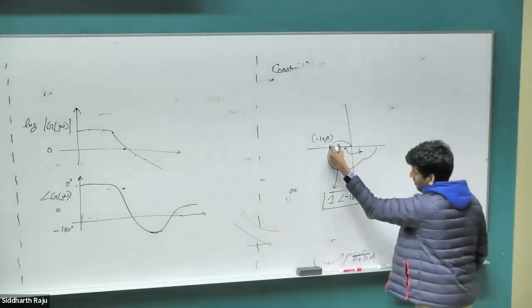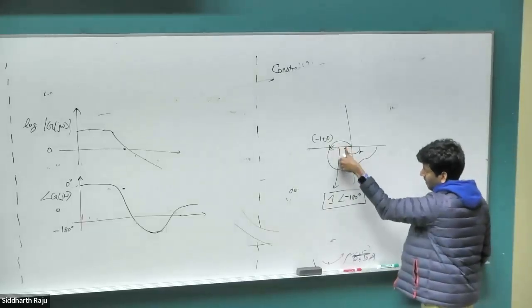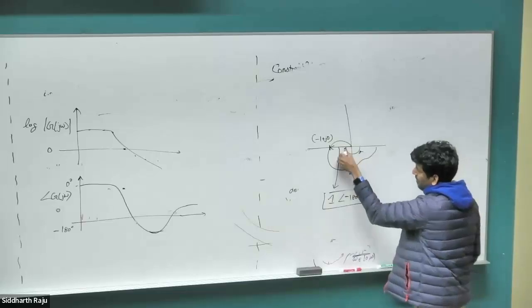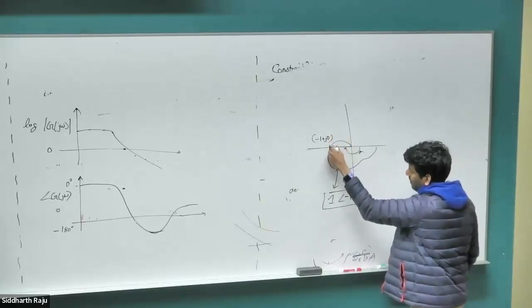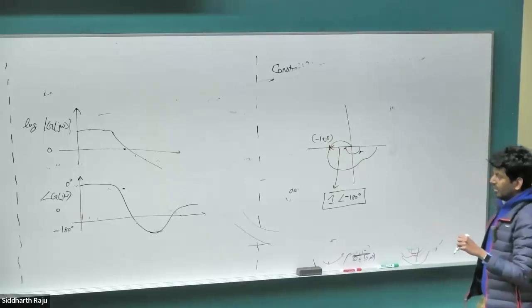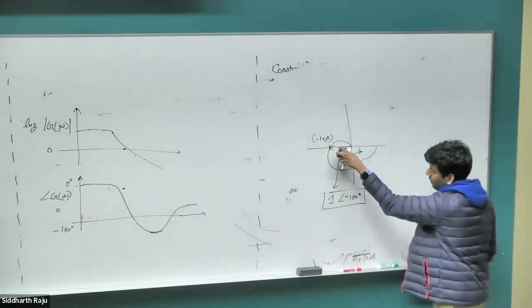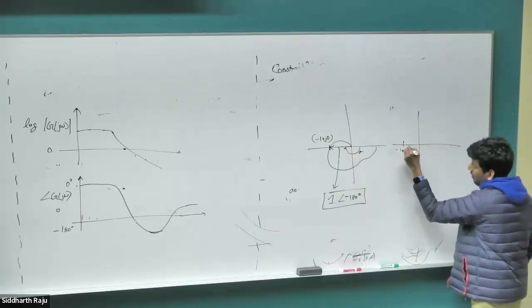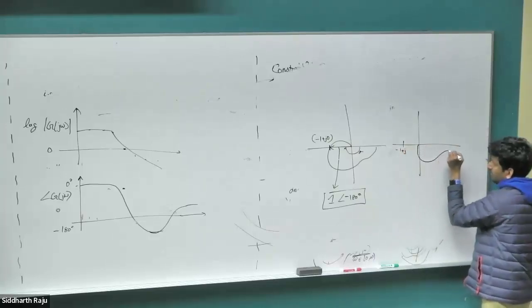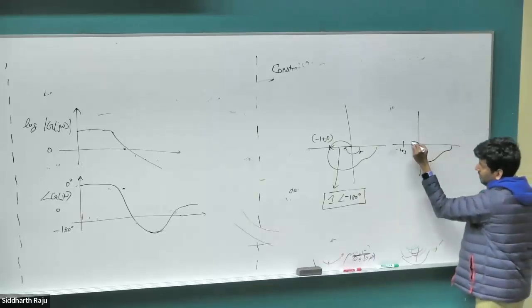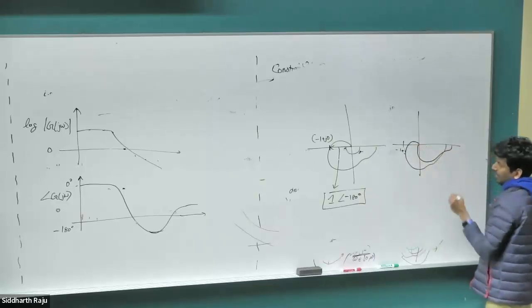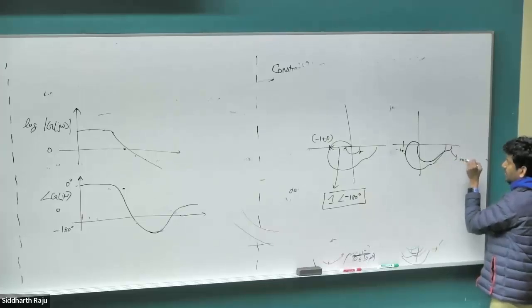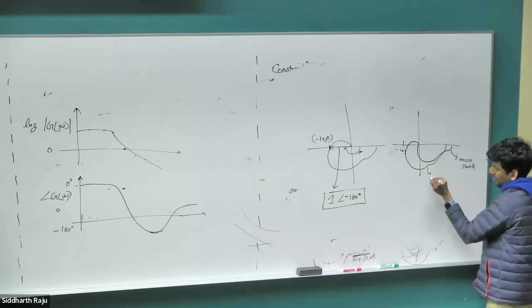If our curve is somehow able to collapse within this region, turn a little bit around and collapse, it will be stable. If our curve goes a little bit outwards, it will end close to -1 plus j0 and it will become unstable. And the farther away from it we are, the more stable our system is. So if I had -1 plus j0 and I had a system that looked like this versus a system that looked like this, okay? The second one is more stable. Both of them are stable. This one is slightly less stable, but it's still stable though.